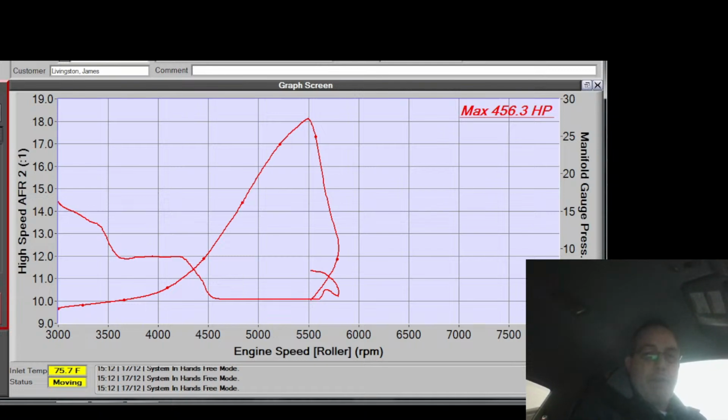Get an occasional pop out the tail right now. My air-fuel is 14.4, which is my target, so my trim is only 2%. But I'm getting a pop as if one of my cylinders is actually still a bit lean. My commanded fuel final is 17.7 because the evap is currently running, but it's obviously set up correctly because my trim is only 3 or 4%. There's that pop again.